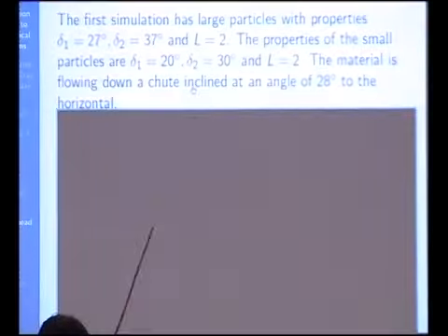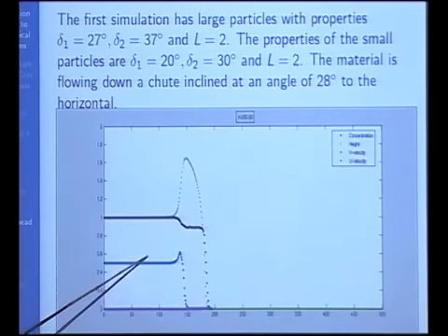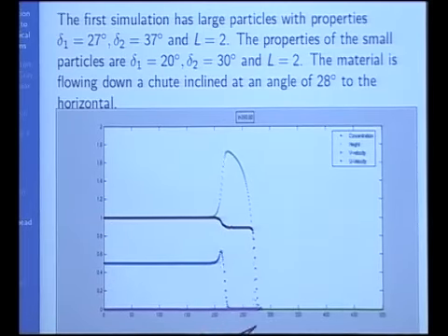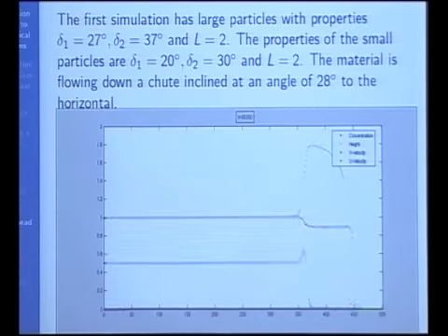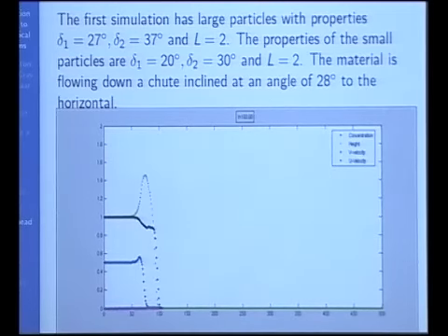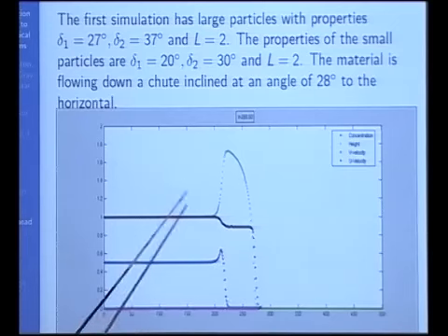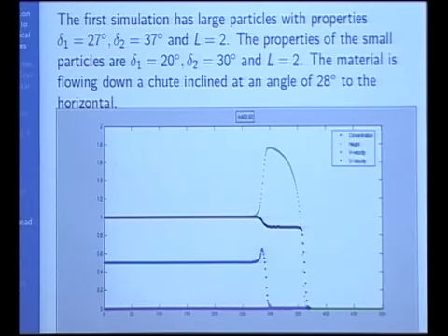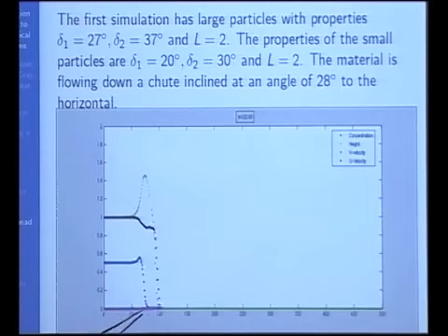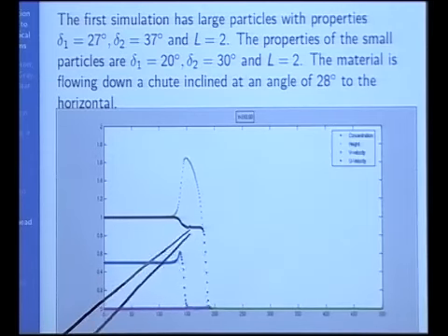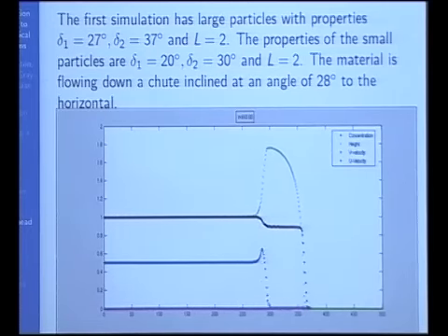If you look at the height profile, you notice we're getting some sort of bulge in the height profile here. So I'll look at the center line numerics, and from that we can say a little bit more. This is plotting it at the center line, where this is the velocity, this is the concentration. Again, you can see this pure rich region of large material. But these flows also form this sort of bulbous head shape. This is nothing to do with, as Jim Jenkins' poster does, water segregation. This is just a perfectly dry model, but with bidispersed material.